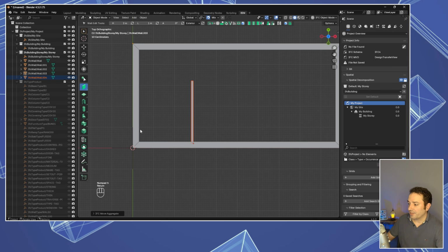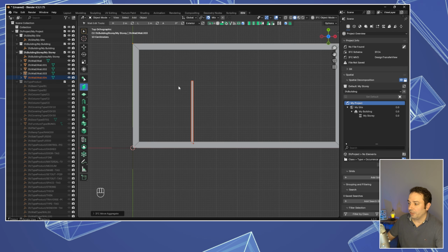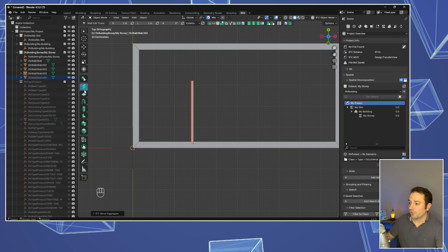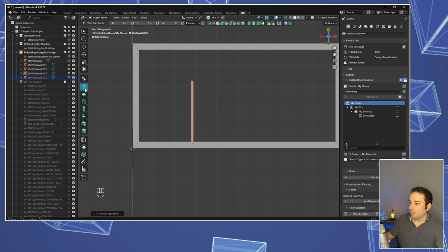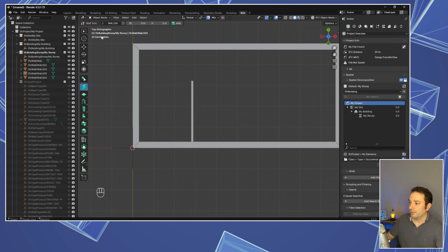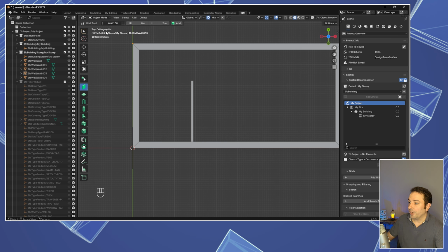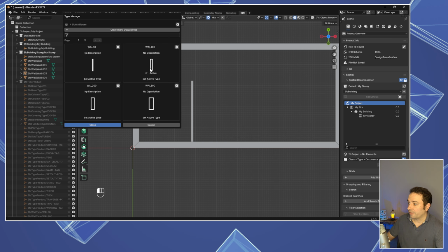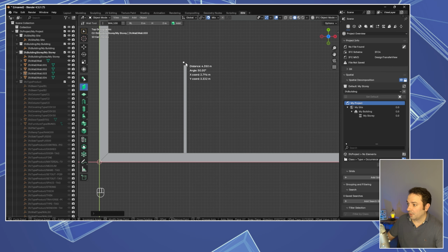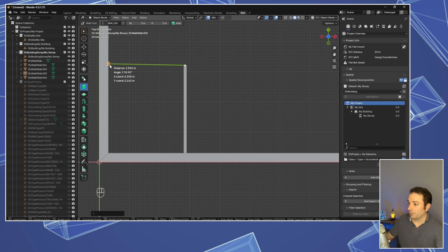So now we have exactly a wall at 2.5 meters from the external wall. So now we can finish by creating the final partition here to close this room. So let's go back here, wall, it's 100 selected, press Add and select the central point of this wall.